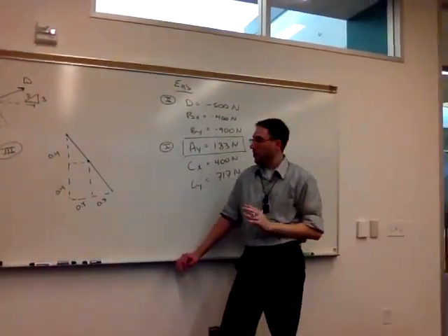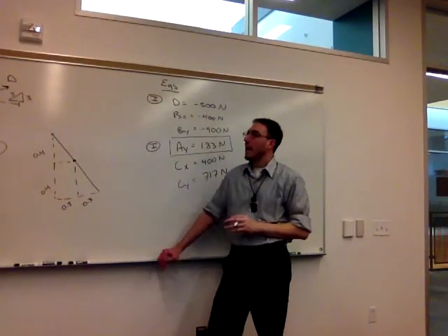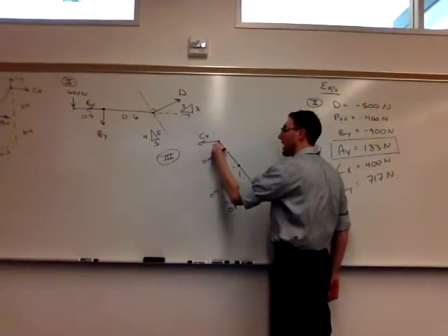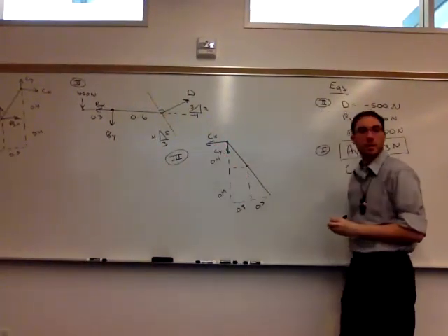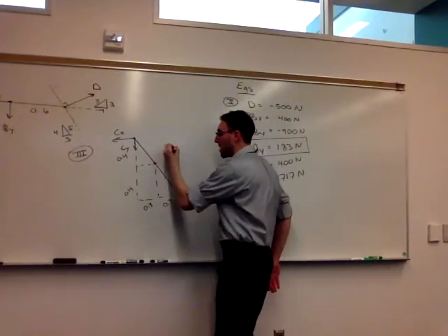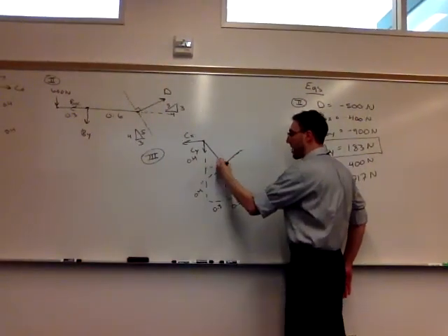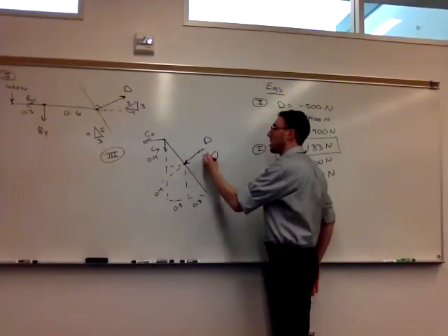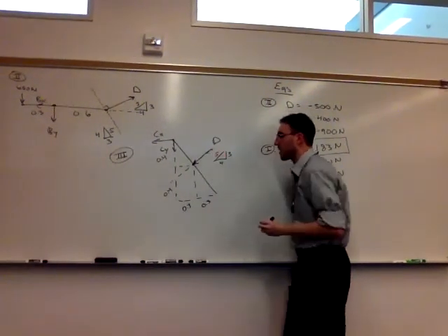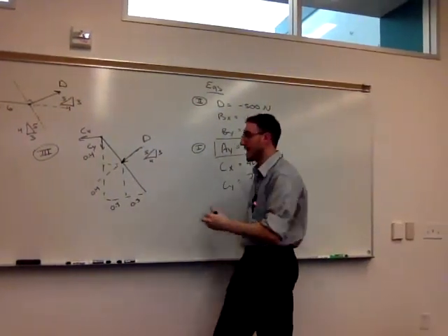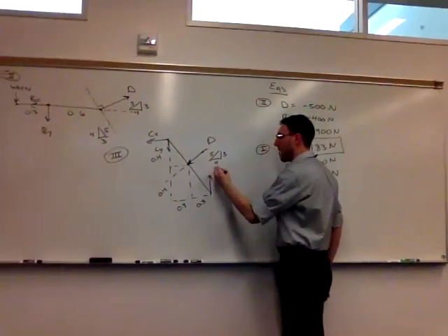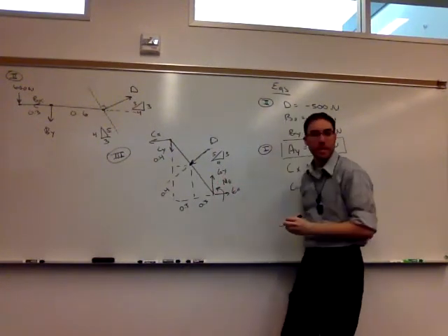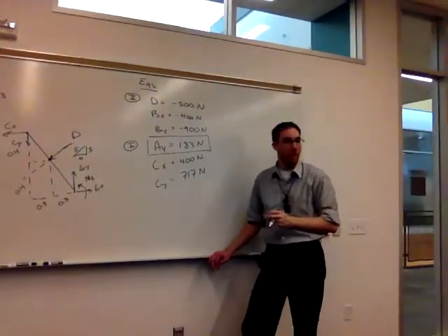So no external forces are acting on this. At C, I've already made the assumption of direction, so I have to draw it CX left, CY down. At D, I've also already made that assumption of direction, so I have to draw it in the opposite direction that I drew it in picture number 2. So the only choice I have left is at E. It's built into the ground, so I'll have an EY and an EX, and there'll be a couple that I will call M sub E acting at E as well.